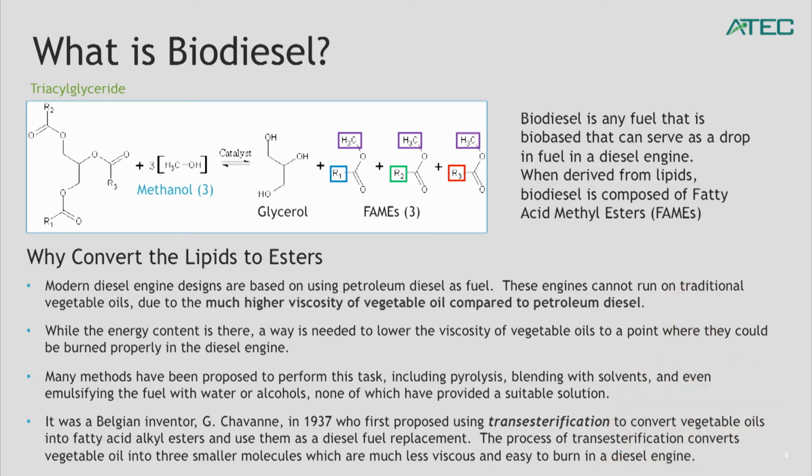Now, the biggest problem with these oils and why you have to undergo some sort of conversion is this viscosity factor. If you didn't match the viscosities better, then you'd have to change out the fuel pump and the fuel delivery system, and that's a cost that makes it impossible to use them back and forth between fuel sources. Some of the ways that we tried to get around this were by thinning the oils with water and alcohols and other things, and none of that really ever worked out very well.